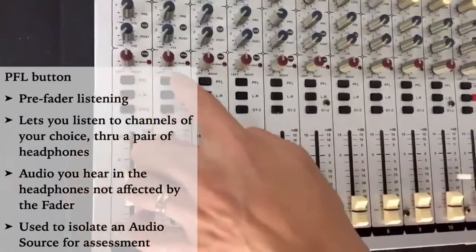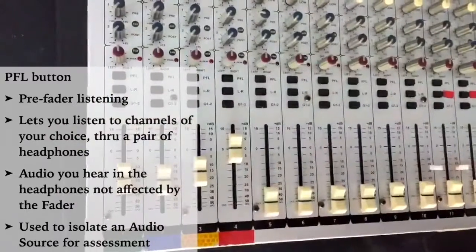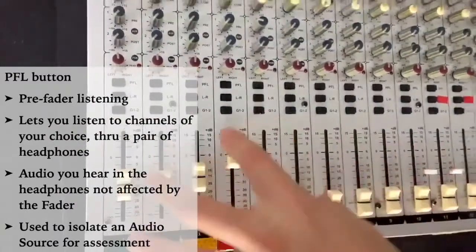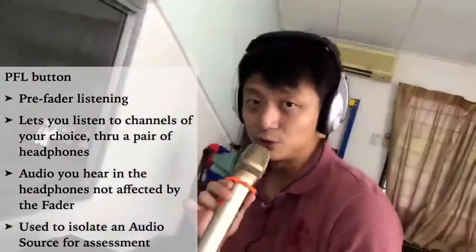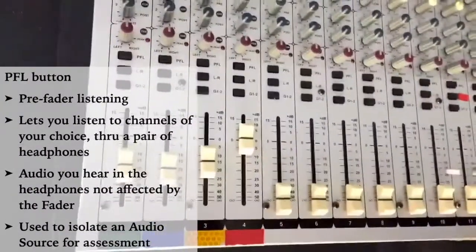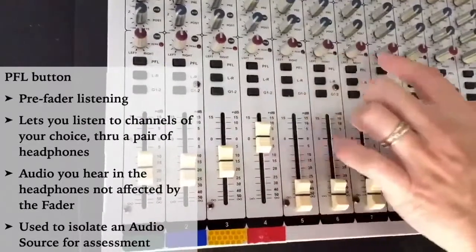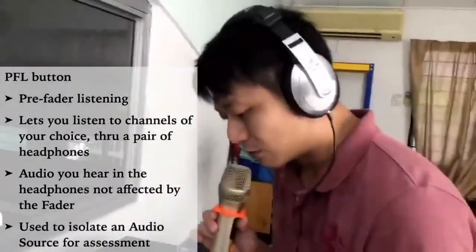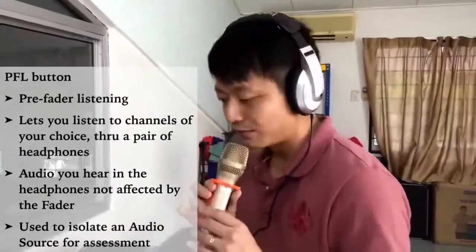So now you can select, out of all the sources here, whichever PFL you want to hear in your headphone, and you don't want it to be affected by the setting of the fader, the volume control. Then you choose PFL, and you can hear it separately in your headphone. PFL allows you to listen to your audio without being affected by the volume control. It is very useful.